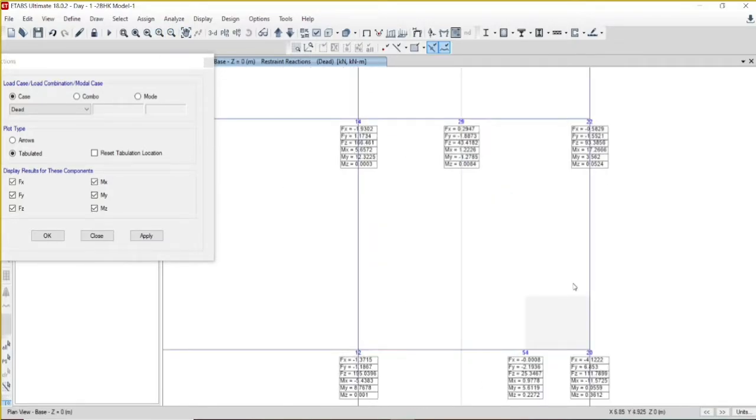We can see this critical area: 166, 43, 93, and here you have 195, 25 and 111 kilonewton. This is around 10 tons of load occurring, and around 195 kilonewton of load due to dead load only. Due to only dead load, you are carrying this much Z. Regarding the moment, this is the X and this is the Y direction. In the Y direction you have a high moment of 12.32 kilonewton-meter, and at all the other portions you have lower numbers.